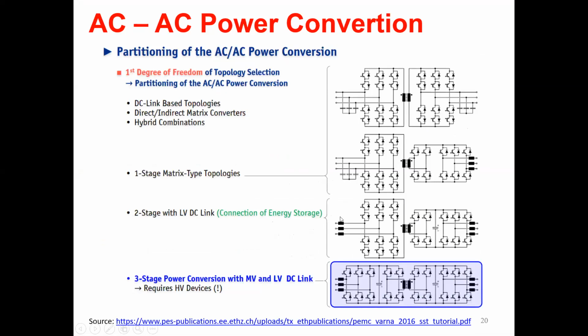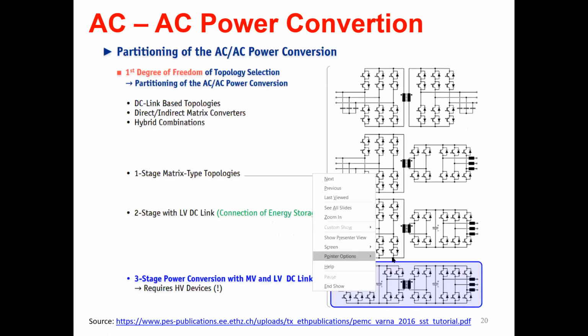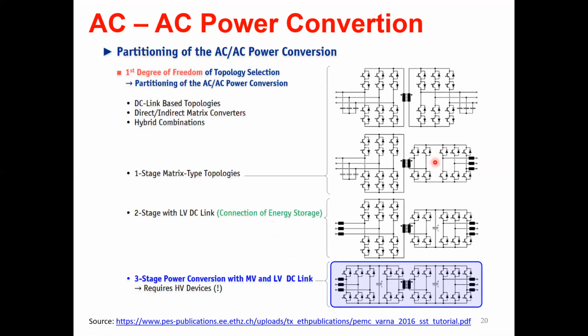Okay. So in this case, whenever there is no capacitor, it just means that this link is supposed to be a pulsating DC link, like a full wave rectifier waveform. If you have a weak DC link, because it's a three-phase system, it is not going to be a full wave rectified waveform. It will almost look like a 6-pulse rectifier waveform, but it will be chopped, because this is actually a three-phase rectifier.